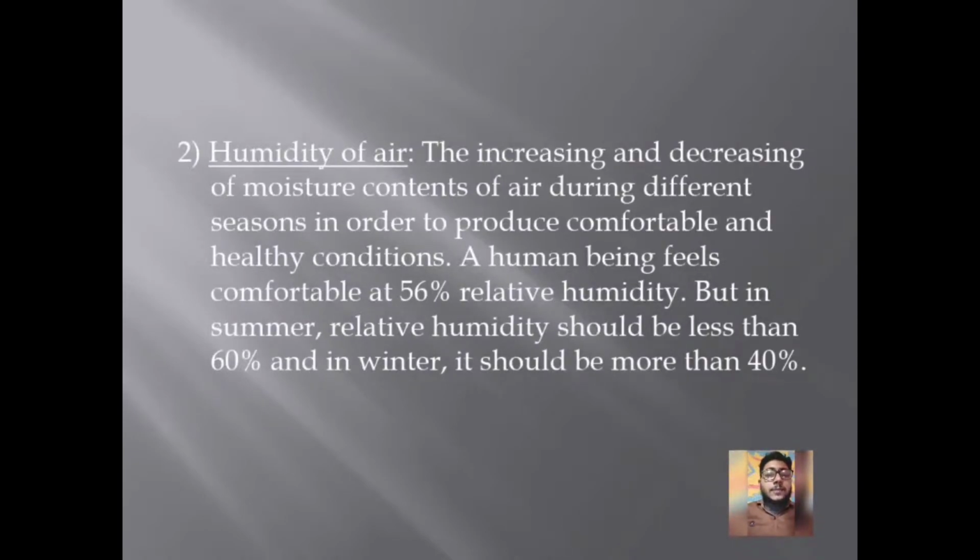High humidity environments have a lot of vapor in the air, which prevents the evaporation of sweat from the skin. In hot environments, humidity is important because less sweat evaporates when humidity is high. The evaporation of sweat is the main method of heat reduction. When non-breathable, vapor impermeable personal protective equipment is worn, the humidity inside the garment increases as the wearer sweats, because the sweat cannot evaporate. If an employee is wearing this type of PPE, the humidity within the PPE will be high.